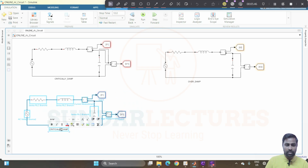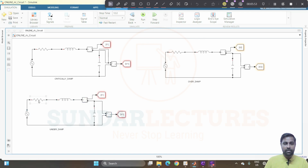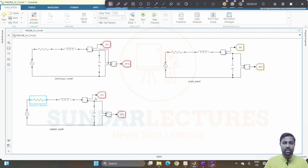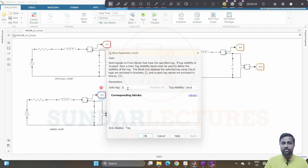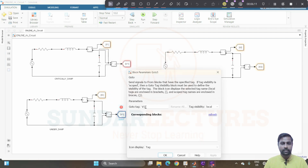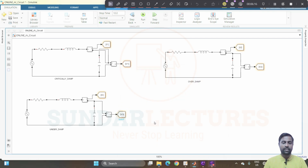We have seen this one in the previous class. We have seen all these kind of things. This is under damped, right? Under damped. For under damped, what is the value of resistance? Resistance has to be low, and we have taken it as 100 ohms. So please refer my previous class. You can see this, and this tag has to be different, right? So it will be I3, and this tag has to be V3. I'm just taking it to be V3. That's all, right? So we have created everything.